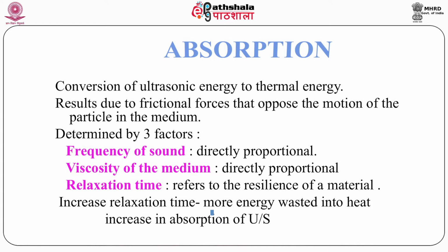Second is the relaxation time of the medium. An increase in relaxation time increases the absorption of the sound wave. Third is the frequency of the sound wave. The higher the frequency, the more the absorption. So a more viscous liquid, more absorption; higher relaxation time, more absorption; higher frequency, more absorption.